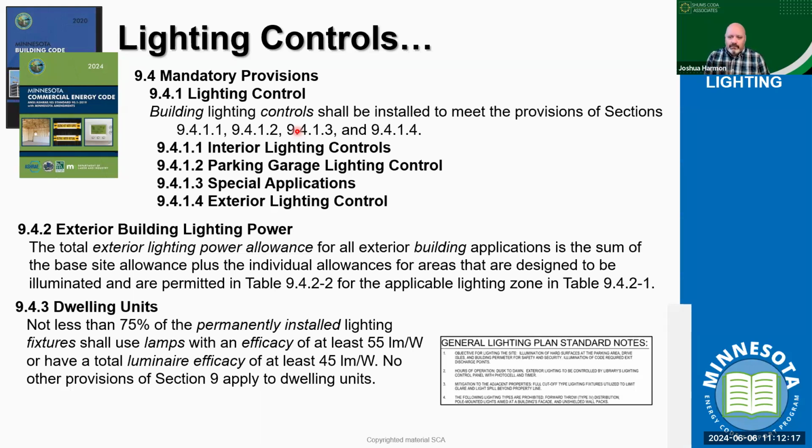One of the examples that the code provides recognizes if we're utilizing timing allocations for buildings that don't operate 24 hours a day, right? So I've got a project that I'm very familiar with that they close at 5 o'clock, and at 7 o'clock they're on a timer and their lights turn on every day. Now at this time of the year, at 7 o'clock the sun is still out, but yet their lights are on a timer. They're not on a photometric control, a photo cell control, right?